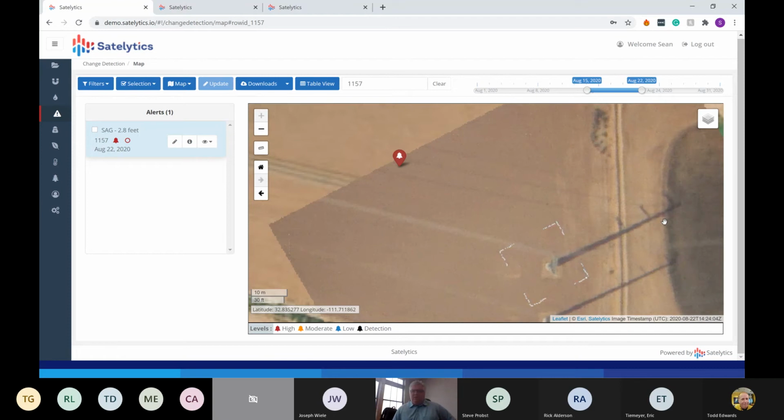What I was illustrating was our community in the power industry. We can see the poles and we can see the cross members. What we can't see are the power lines until the resolution gets to 8 centimeters by 8 centimeters or better. And that now brings into play vegetation height to the line sag coefficient.